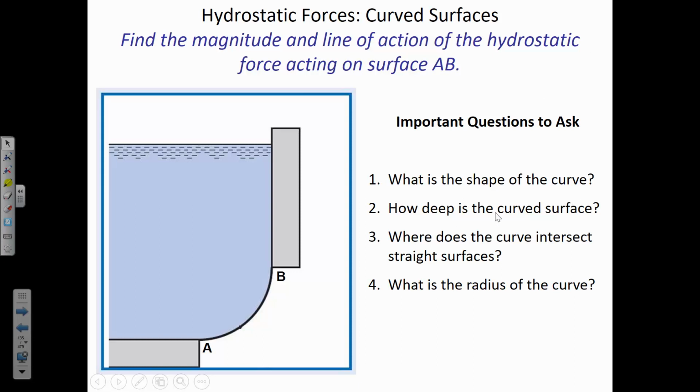One of the important questions is, how deep is it to the curved surface? And why do you suppose that's important to know the depth to the curved surface? It's to find the pressure. And so just when we had flat surfaces, for example, we wanted to know the pressure at a certain location because that's what the force depended on. And it's the same thing here. You want to find out what depth is involved so you can find the hydrostatic force that's acting horizontally.